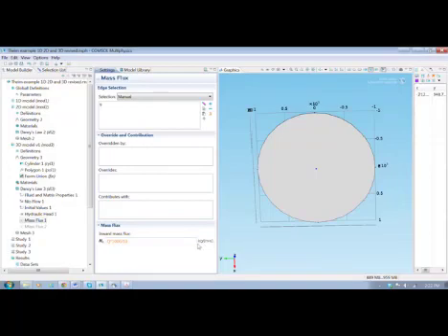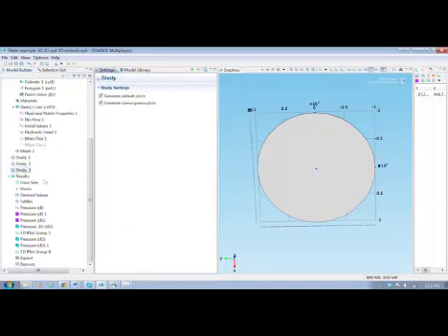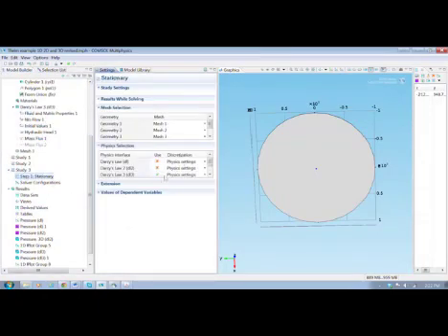So that'll give you the proper entity for this line source. These are the units that it's looking for, and you can see that it's a little bit different than the units of flux that we typically recognize as an entity per length squared per time. But nevertheless, the reason for that is because this is a line source that doesn't really have an area. So that's how you set it up, and go and run it using this study here that is set up to run just that last model.